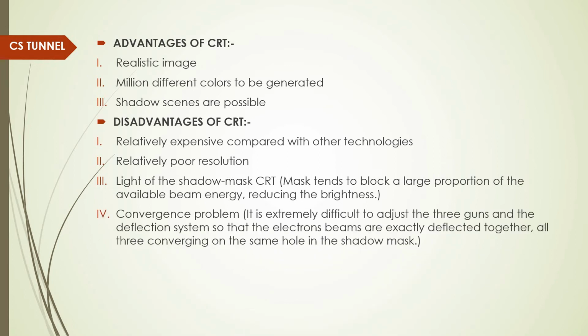Convergence problem is another disadvantage of CRT, which means it is extremely difficult to adjust the three guns and the deflection system so that the electron beams are exactly deflected together, all three converging on the same hole in the shadow mask.